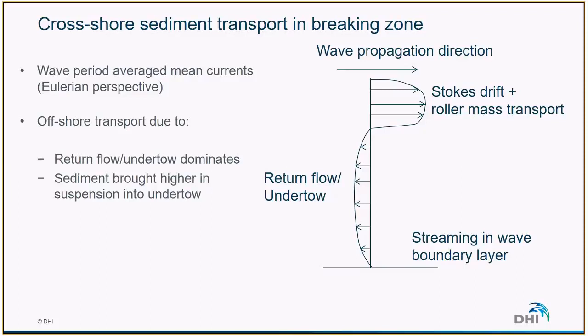And as the suspended sediment profile is different due to breaking, we have different contributions for the sand transport. So in the breaking zone, we can say that usually the return flow or the undertow dominates. And as sediments are brought higher in suspension because of the turbulence due to breaking, the sediments have a tendency to be transported towards the offshore part of the profile.